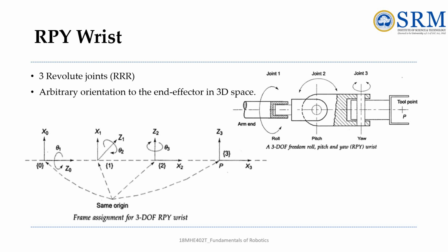Okay, so along the roll, here there is no link length, so it is 0, and here you have to see the degrees of rotation about x-axis, that is the parameter alpha. So you know that you have to calculate 4 parameters, right? That is the link length and twist, that is alpha, and offset and theta, the roll angle. Okay, you have to calculate all this.